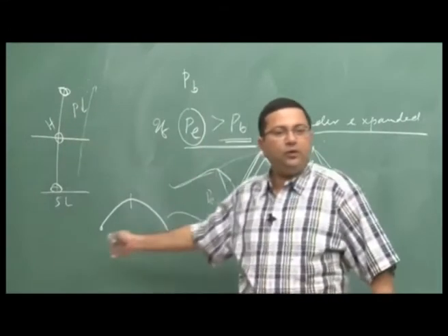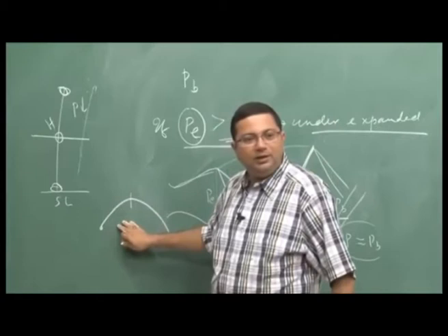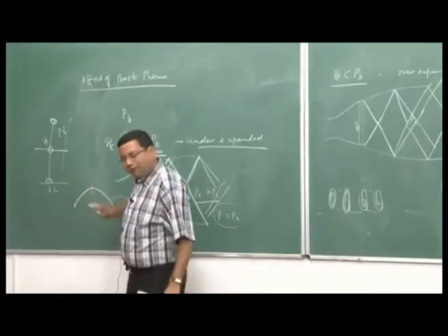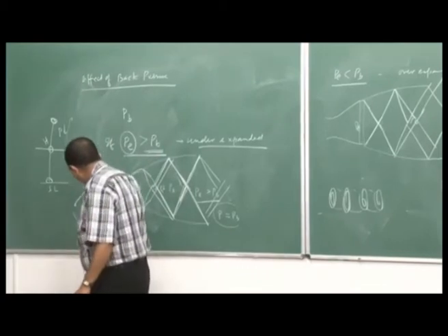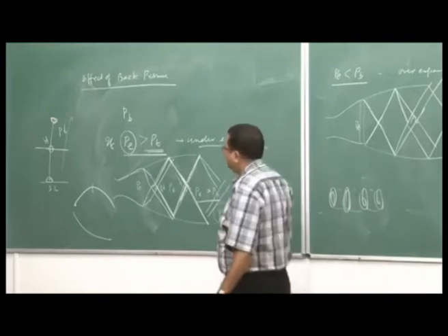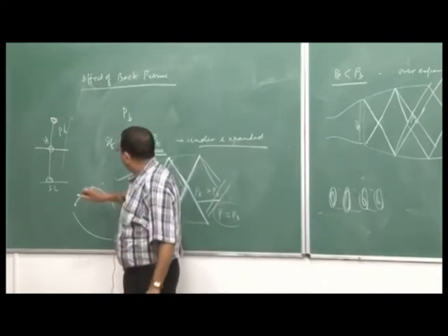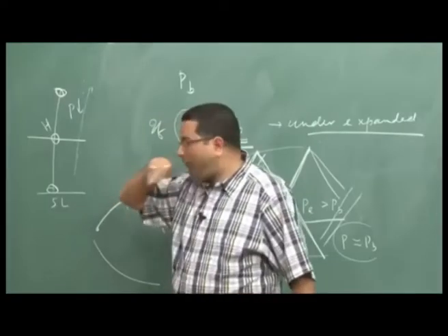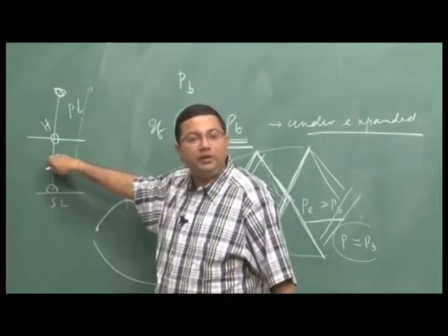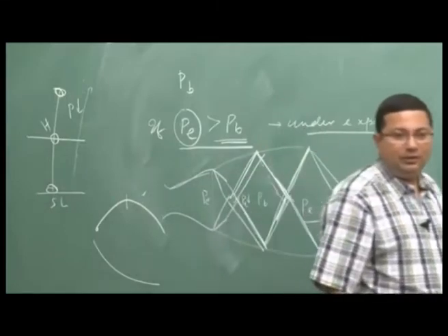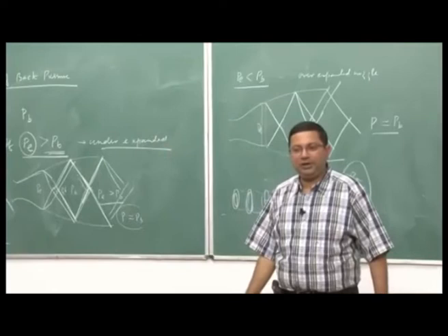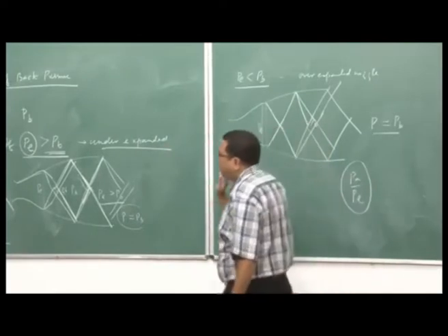Now, depending on the mission requirement, we design it like this. So, this is the best possible scenario. For everything else, we have a continuously dropping thrust as we go up. Therefore, for all practical applications, the nozzles are not designed for either sea level or the maximum height. It is designed for somewhere in between to have the ideal condition, so that it goes across the optimum condition while operating. Okay. That is one way.